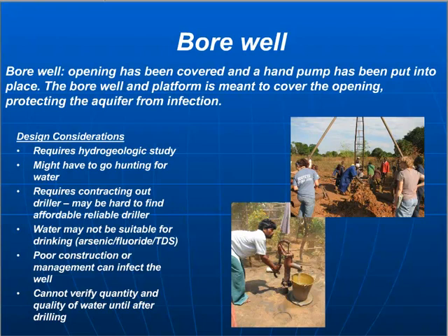In some countries, they seem to have local hydrogeologists that sometimes you can contract out the work. Some chapters have hydrogeologists on their team and can really do a good investigative assessment to get a good judge of whether or not there will be a lot of water. Sometimes you have to really spend a lot of time talking to different drillers in the area. It can be challenging, but you do need to have some sort of hydrogeologic study to make sure that it's worth the risk of drilling a well.